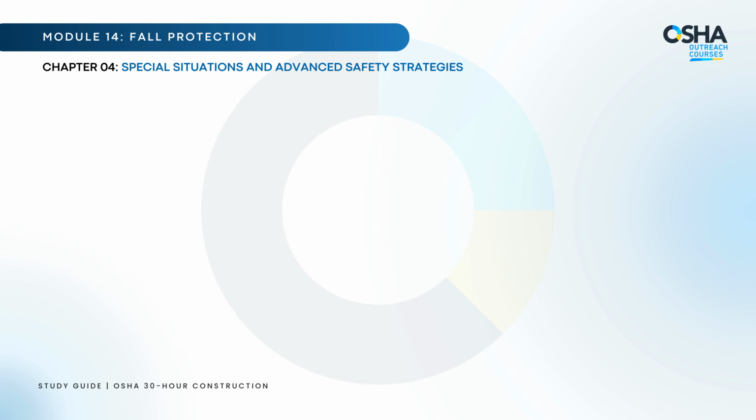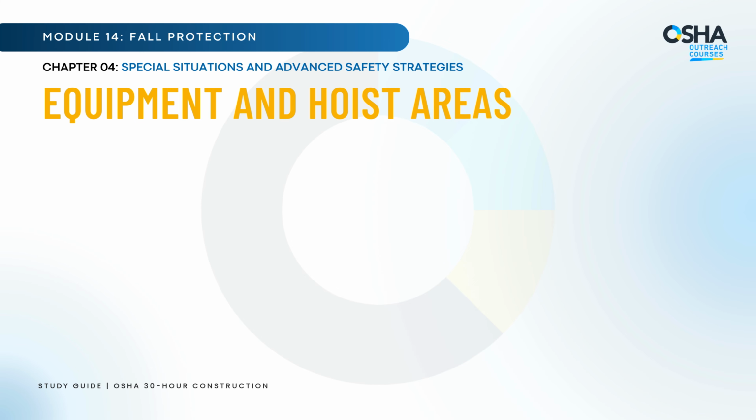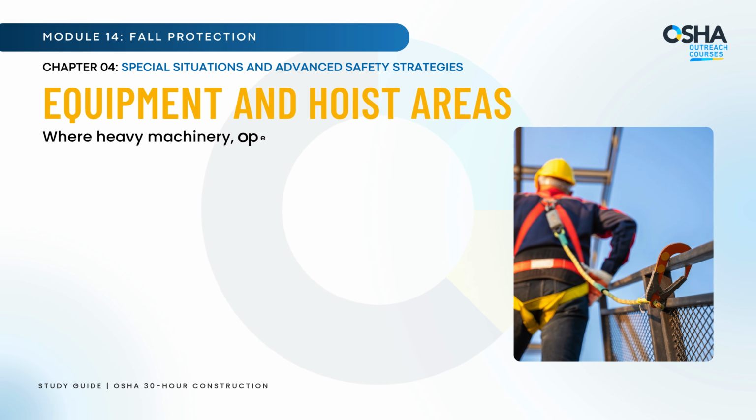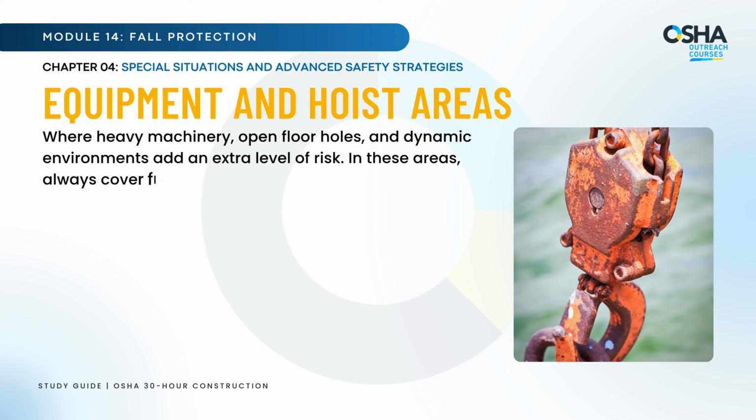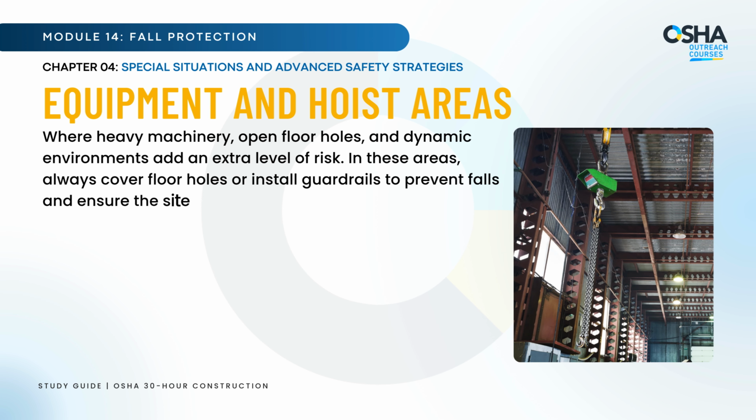Now let's focus on equipment and hoist areas, where heavy machinery, open floor holes, and dynamic environments add an extra level of risk. In these areas, always cover floor holes or install guardrails to prevent falls and ensure the site is clear of trip hazards.